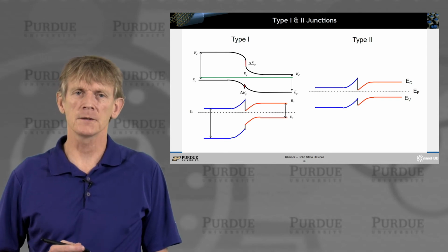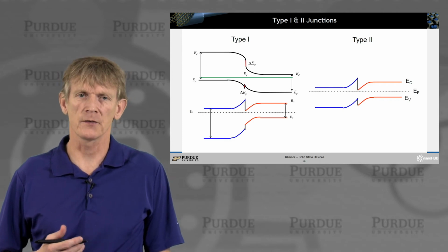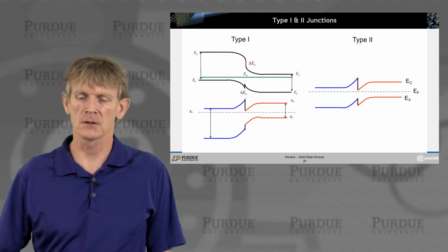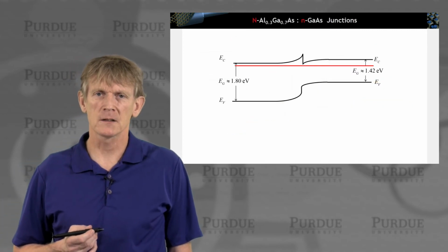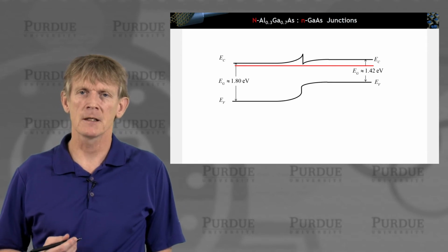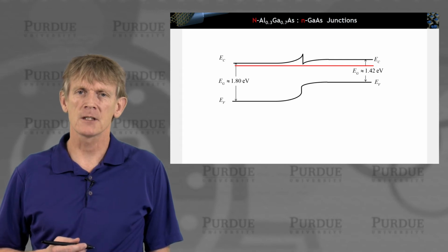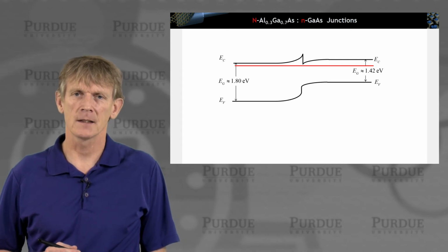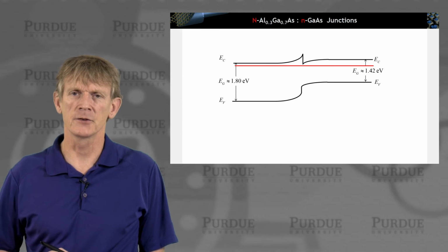They look quite different. You can already begin to appreciate you have really a toolbox of different materials, of different heterostructures you can assemble. Here's another one that's much simpler in a way. Here we're not changing P and N doping, but we keep it both N-type, but we build a junction out of AlGaAs and GaAs. So gallium arsenide on the right, aluminum gallium arsenide on the left, and keep a slightly different doping.